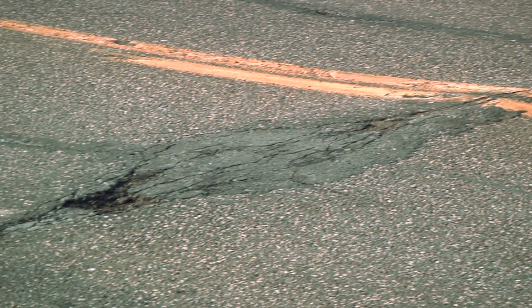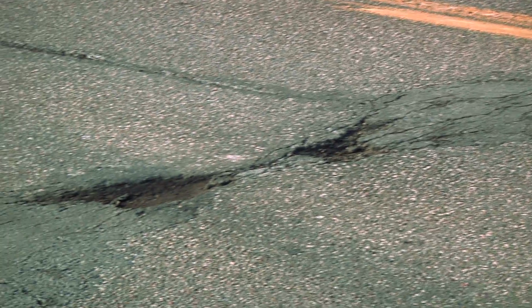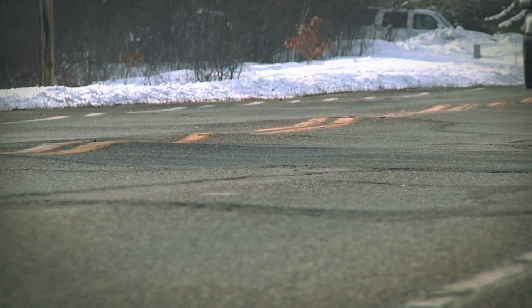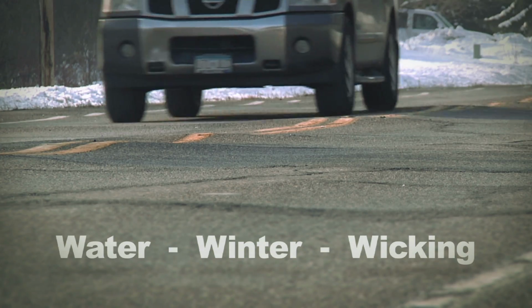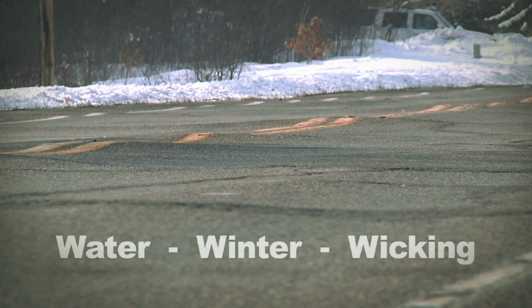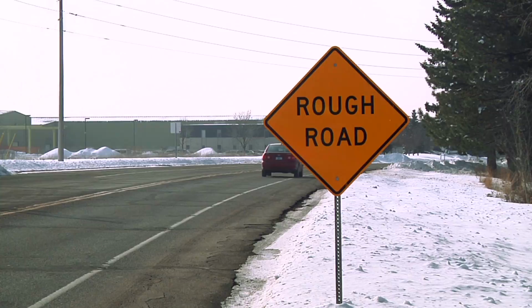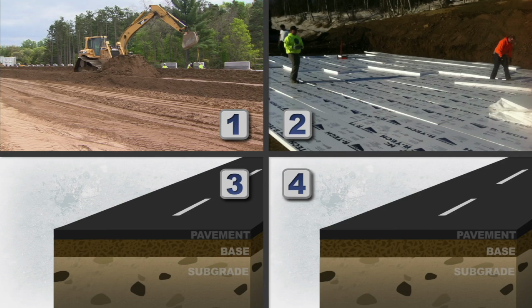As we've seen, frost action is a major cause of pavement damage. The three conditions needed to produce frost damage, water, winter, and wicking, exist in many parts of the world. And the damage caused by frost action is a major cost factor for public works agencies and for road users. But we've also shown that there are several ways to design pavements to resist damage from frost action. Since winter is unavoidable, the goal of all these methods is to focus on the water and the wicking.